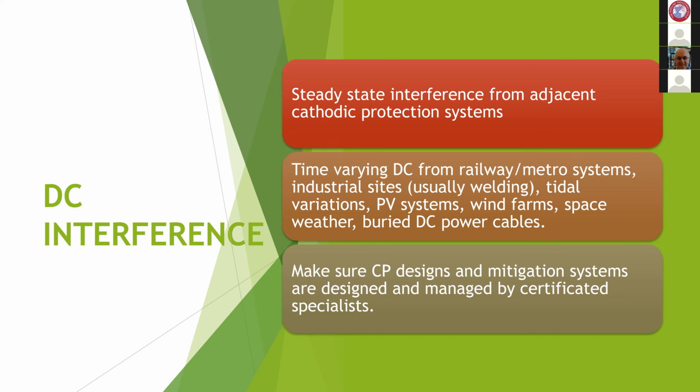And on roads, we measure those in percentages these days, but we used to measure them as a ratio, like a 1 in 3, a 1 in 5, a 1 in 10. But basically, the higher you lift that flat piece of wood, the faster and more easily the ball will roll down. If there's any friction in the ball, you need to lift it higher to get it moving, to get a bigger gradient. Well, it's exactly the same with voltages in the ground, except you can't see those.